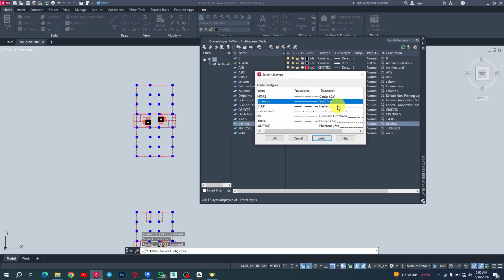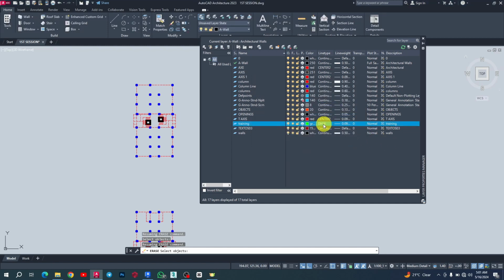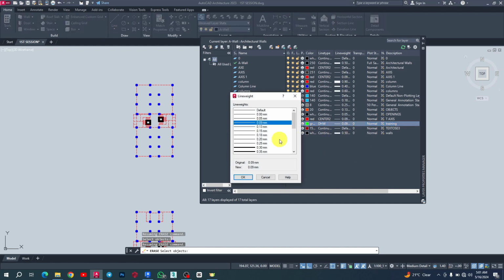So now if we go to our drawing here, we should see DHW, that is hot water line here, domestic hot water line. So I don't want to use that one. Or let's say we want to use it. For instance, this is it. I just select on it and then I say okay. So you see it appearing here, and you want to give it a line weight.